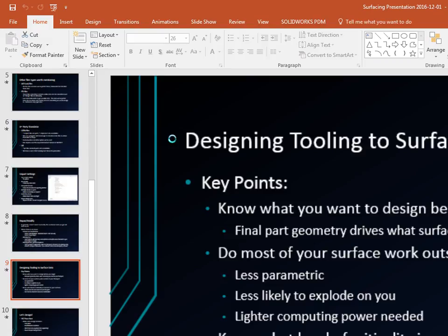Okay, so I've got this as one single surface body now. And so now I can fillet it. You can't fillet it unless it's a single surface body. If these were two surface bodies, it's not going to let that happen. So you're saying to put a fillet in here. Or say if I wanted to fillet it bigger than that, you know, first tangent or something like that. Right.